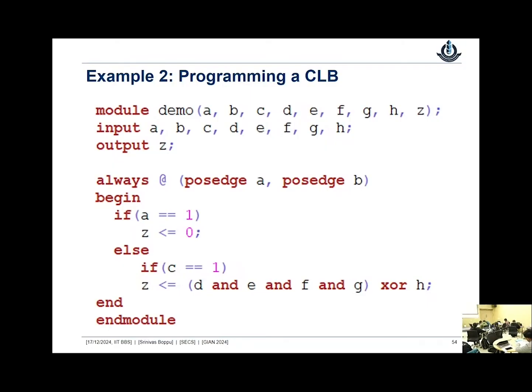On the first, any of the examples you can take and solve that. We have a design called an 8-bit adder circuit. You can think of it as a carry propagate adder or a carry look ahead adder, and implement that also using the given slices. We can again take 15-20 minutes, not an issue, using that LUT, and then you also have to realize your D flip flop.